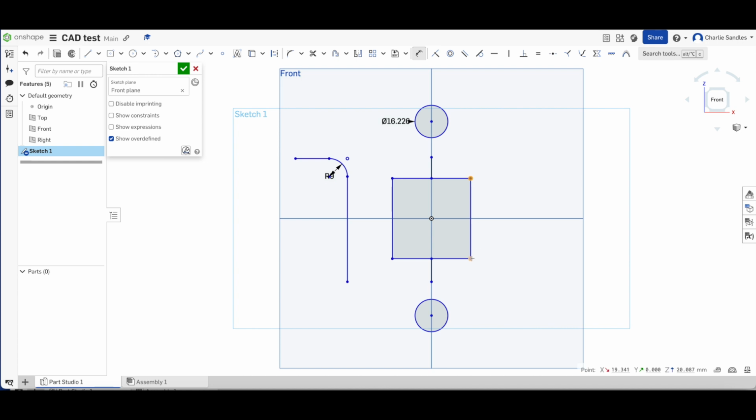So for example, I might want to have a look at this dimension here, and you can see that once I've selected the top and bottom points of that line, it's brought out this black dimensioning line here. And you can see that once I click to set that, this box here has appeared, and this allows me just to overtype to whatever I want that dimension to be. So for example, I might choose to make that 45 millimeters, and you'll see that that has changed that there.